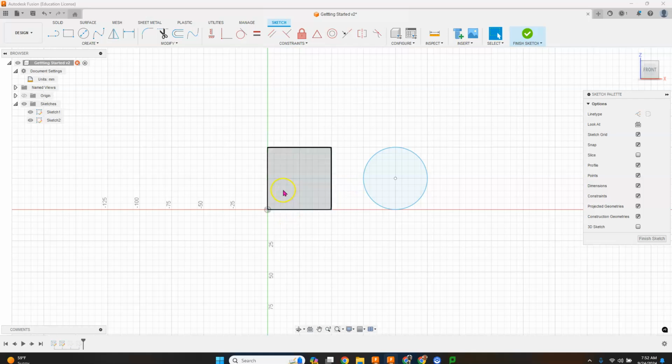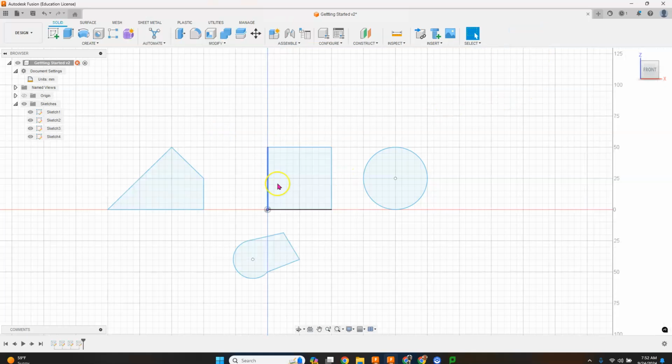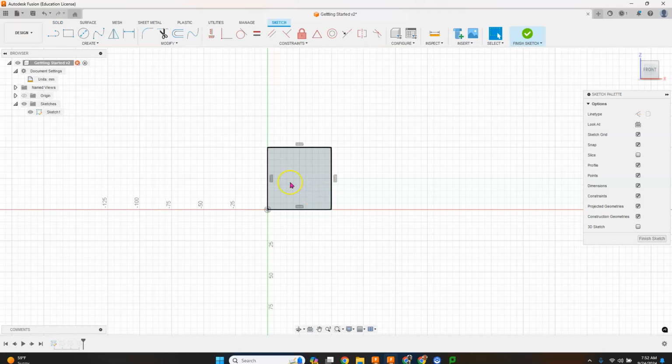Now, after we edit sketch, we're going to be back in the sketch. If you hit Finish Sketch, it kind of goes back to where you were before. At the same time, I'm going to actually just start with my little rectangle here. So if I right-click this and edit my sketch, now you can see that I'm working only in the rectangle.